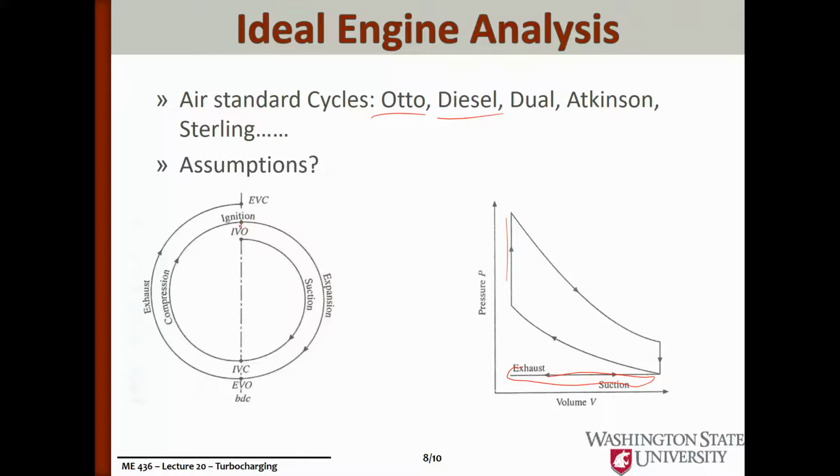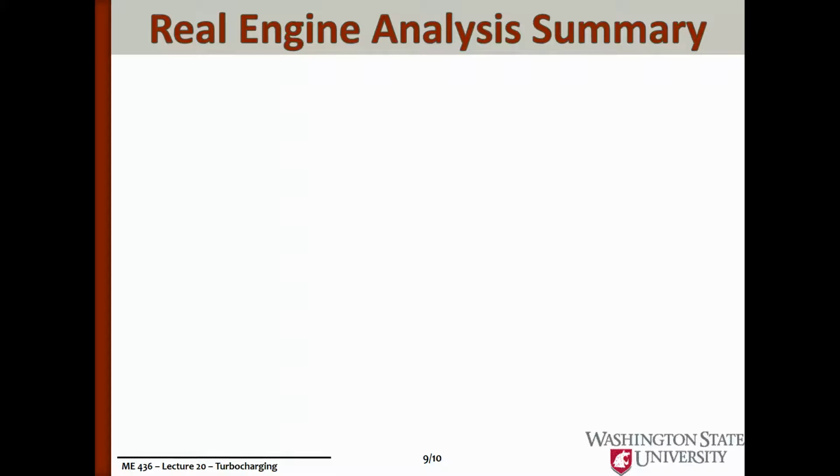We almost always, in those basic assumptions, assumed that the valve openings were instantaneous and that they occurred at top dead center or bottom dead center, so that we separated out the 4 strokes of the cycle to just be an intake stroke, a compression stroke, an expansion stroke, and an exhaust stroke, with combustion happening instantaneously. So those were the ideal things we did, and then we worked through a whole host of modifications to the